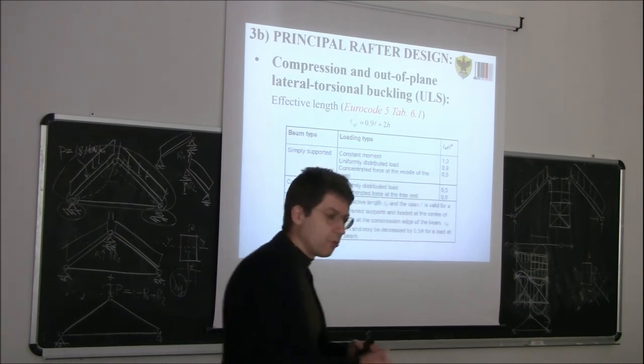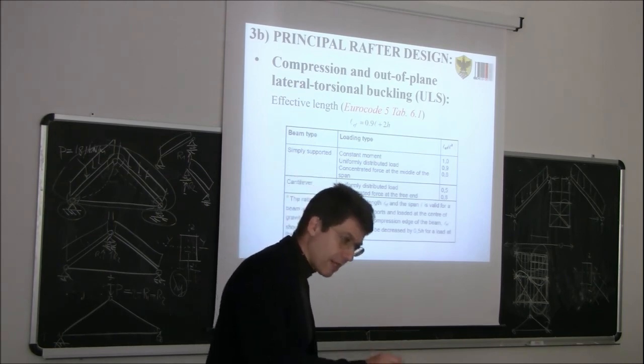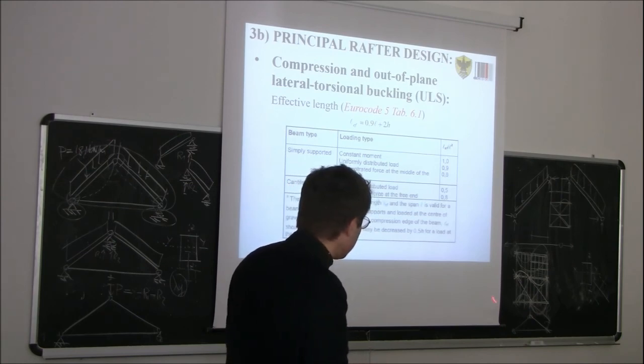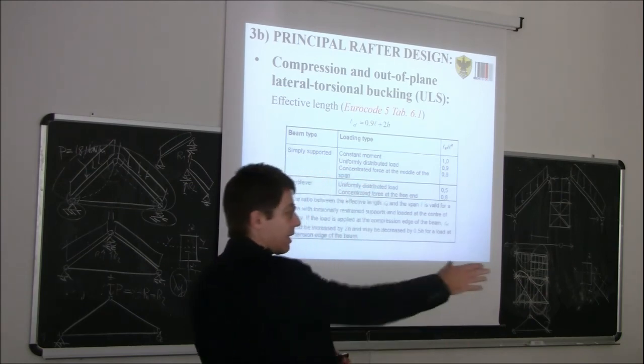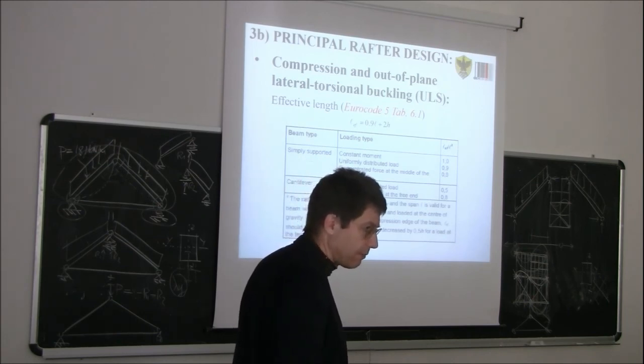But if you do this, it's not because you have to. It's just because the size of the rod may become big. Strictly speaking, you just need one, and all the others that are connected with the purlins are okay. It's clear?